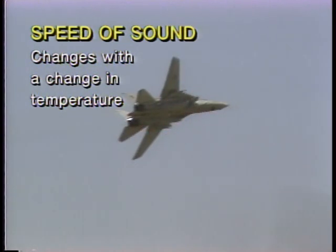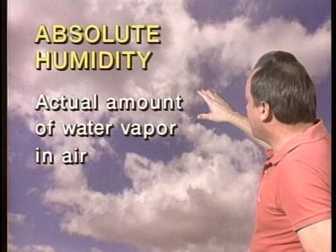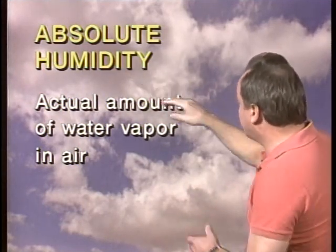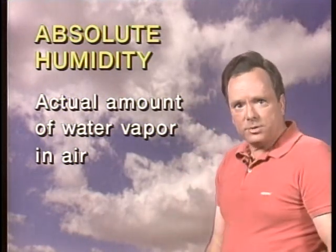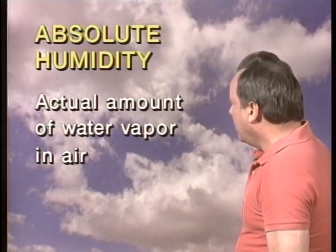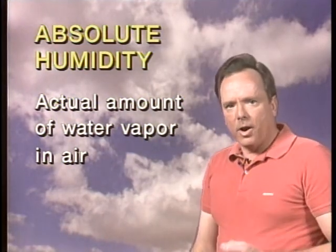All right, now let's talk about humidity. They're going to ask you about water vapor in the air. And water vapor, of course, is vapor that is not visible. Clouds are visible moisture, but when we're talking about water vapor, we're talking about water that has actually gone into the air. And so they're saying on the test, all right, super mechanic, what is absolute humidity? And absolute humidity is the actual amount of water vapor in the air, in the mixture of air and water.